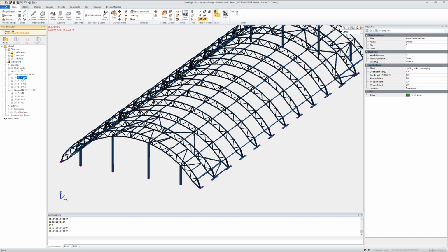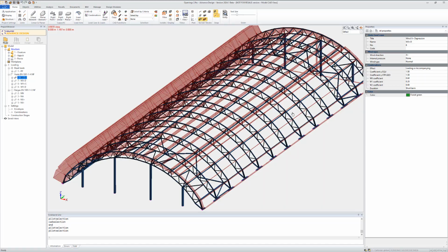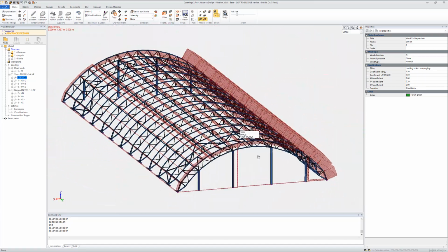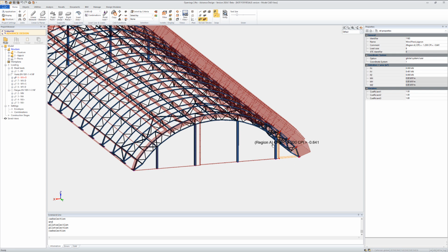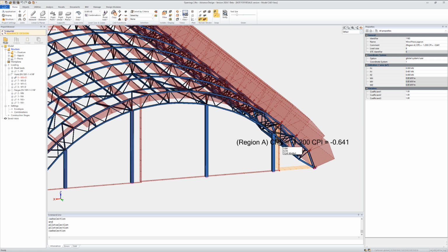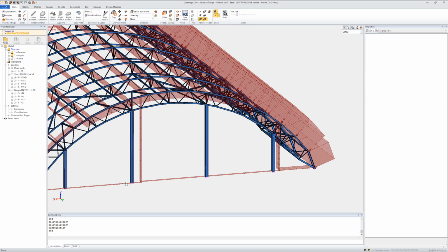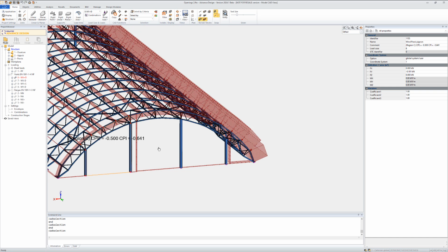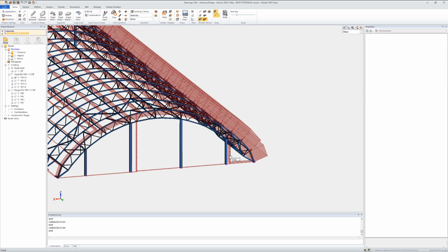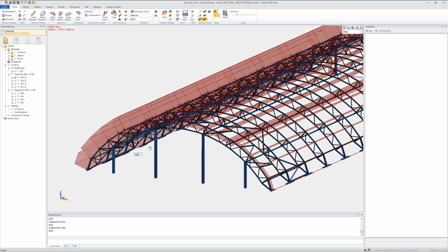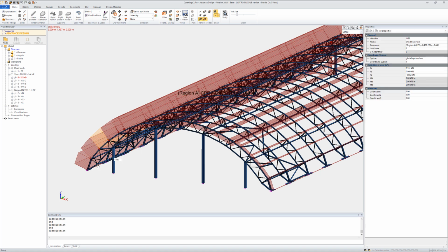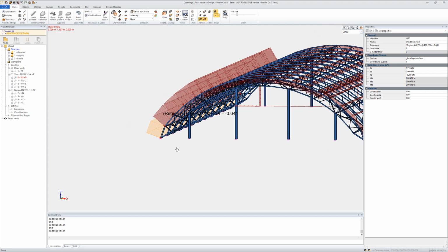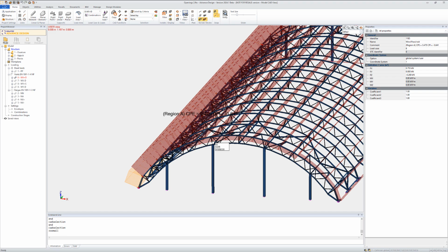And if we check another direction, like a lateral wind, it's a bit more complex, because the other face, the face that we opened, would have a mix of multiple CPE. We have the one from zone E, which is 1.2, but then we would have the one from zone B, 0.8, and then zone C. So to take 90% of something, Advanced Design will first compute an average CPE value on the other face, the one that we opened, and then take 90% of that. This is how it gets the CPI of 0.64 for this direction.